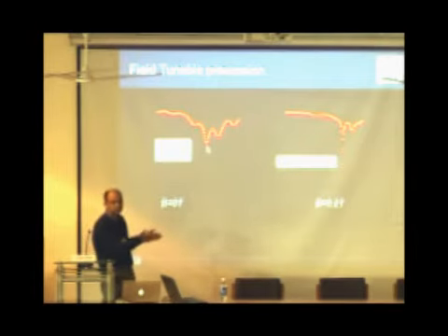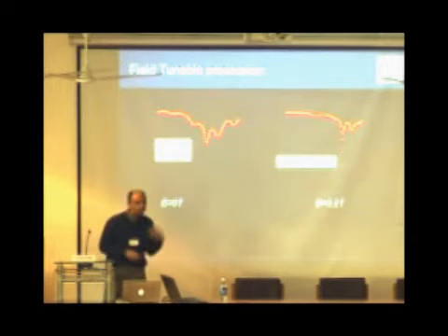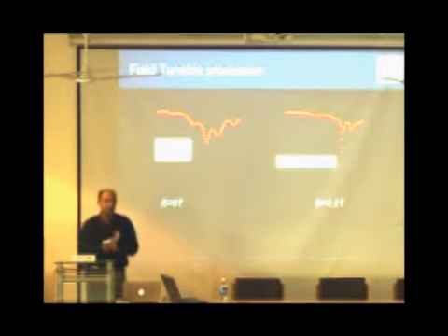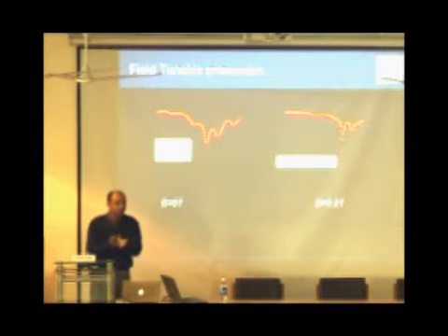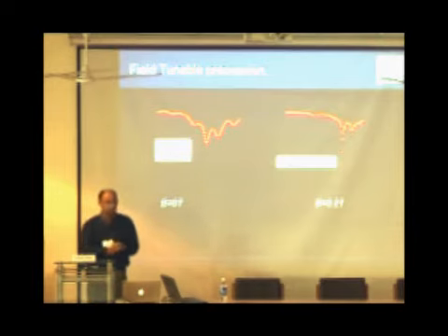So this is in terms of frequency. I'll show you the time domain curves for this as well later. But what it tells you is that certain frequencies, this is acting as a tunable filter. So at certain frequencies it will absorb the wave which is going through the transmission line. At other frequencies it's just going to let it go through.